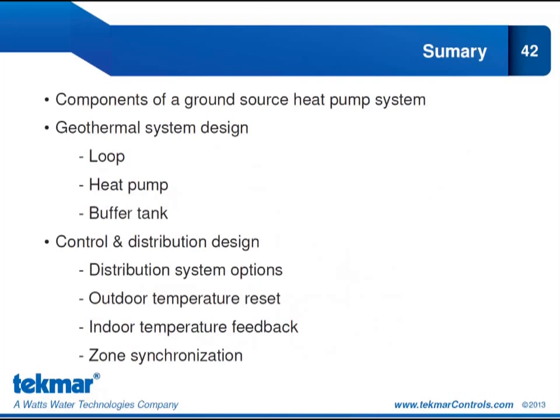To summarize this 3rd module of our Advanced Heat Pump Control training course, we looked at the components of a ground source heat pump system. So we had the geo side, the heat pump and equipment side, and the distribution side, and how the control solution that we choose can have a huge impact on our heat pump and on our distribution. We looked at the geothermal system design. In particular, we looked at the loop design and sizing, the heat pump selection, and the buffer tank sizing, and why each of those is extremely important to the overall capacity and efficiency of our heat pump system.